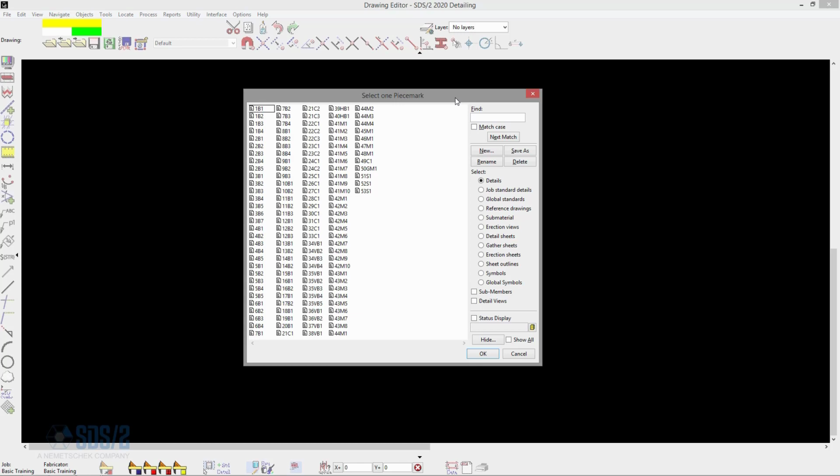To start off with, we're going to talk about our piece marking. The first time you auto-load, it sometimes can be overwhelming, and maybe we got the names wrong. Maybe we have the piece marks not the way we want them for our members. If the piece marking is just wrong, we can simply delete our sheets and re-auto-load with the new piece marking, since there's no possibility of any old marks conflicting with the new piece marks.